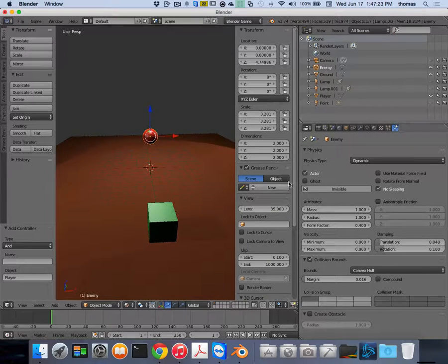Some of it also is the way I've created my object, and I'll tell you this before I continue. I've transformed my object's location, but I've also transformed my object's scale. The scale of my object here is 3 times larger than what it should be, and that's what also drives the size of this stuff here. So, a very, very important thing to do. If you're making an object, like for example a character or an enemy, if we import a spaceship, I'm going to show you how to do actual objects from somewhere else, because let's face it, our modeling days are pretty much done for this course. We want to try and import objects from now on.